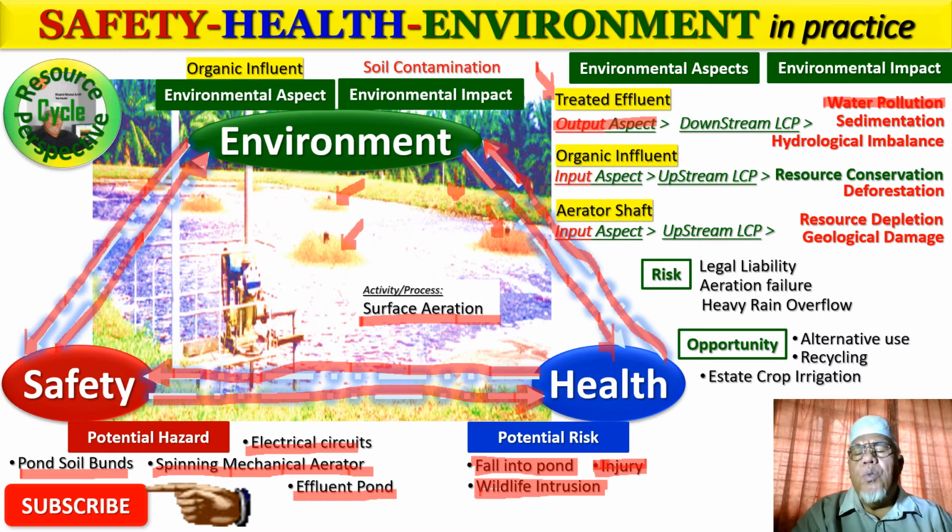And it brings along with it solids. And what happens? Some of these solids are actually dead microbial cells. Some of them are microbes, viable living cells. And they have aeration, nitrification and denitrification occurring as well, despite the fact that they have left this particular pond. And the solid buildup will eventually cause another problem to the environment, an impact called sedimentation, shallowing of rivers.